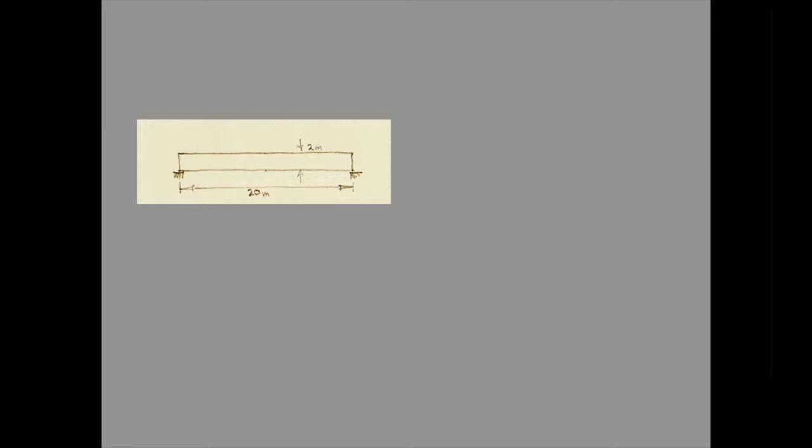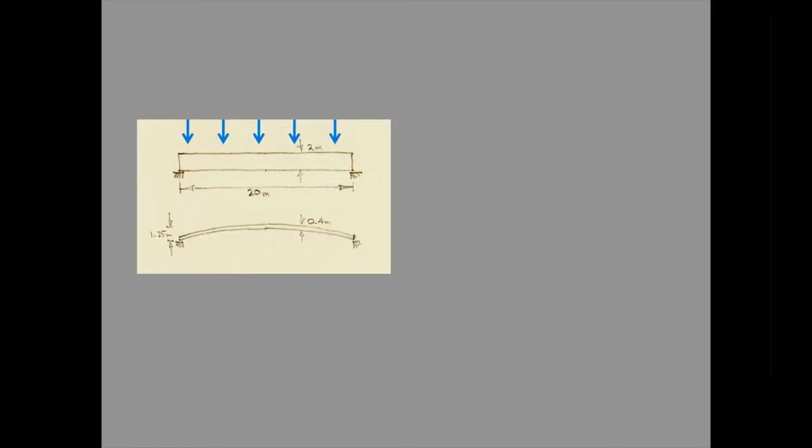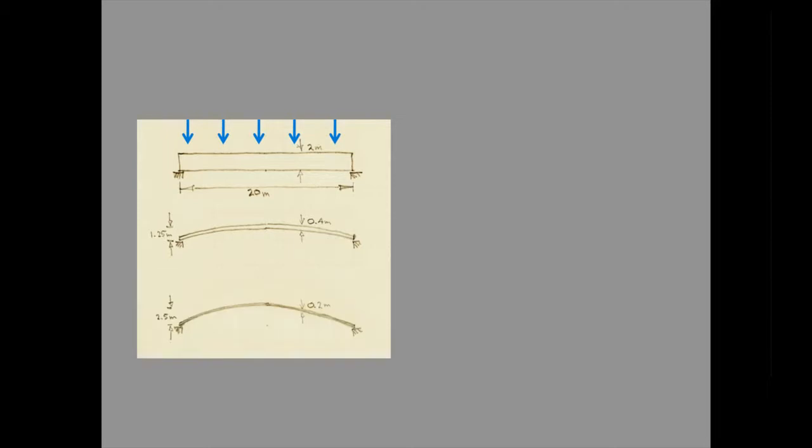The internal force that generates the stress is affected by the form in quite significant ways, and we would find that if we introduced curvature by raising the centre of the beam by 1.25 meters, a depth of only 0.4 meters would be required to contain the stress within an acceptable level, due to the way in which the change in shape affected internal force. If we raised the centre further to 2.5 meters, the effect on internal force would be such that a depth of only 0.2 meters would be required.